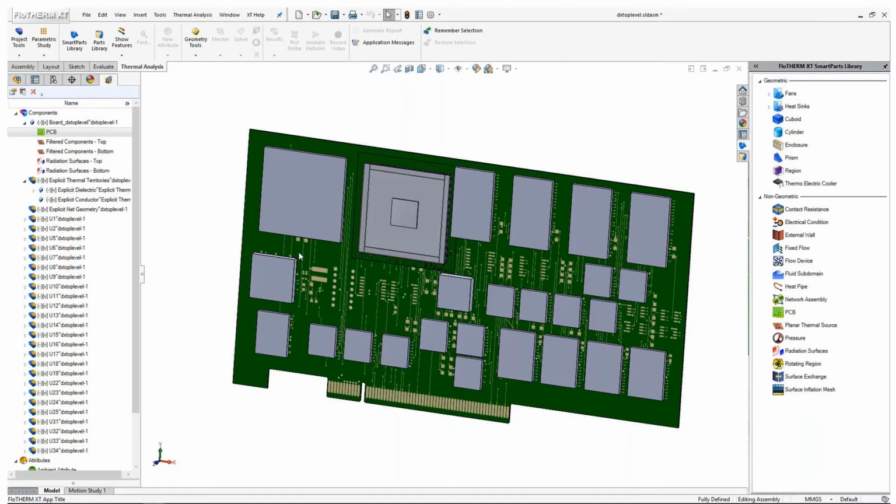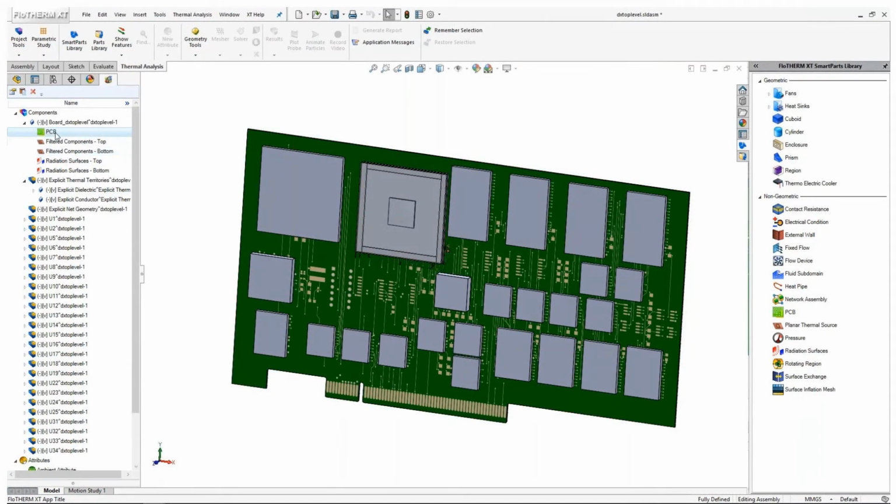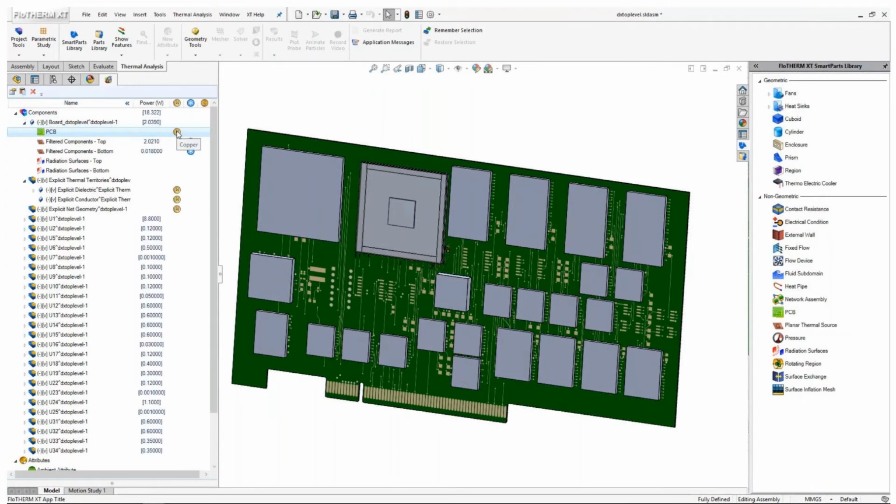So to summarize what we have done so far, we have the material definitions assigned on different components that we have, thermal attributes assigned, and we got the total power defined as well using the CSV file. So let's look at the thermal territory which we have over here. Before that, let's have a look at the attributes which we have. We can see that what we define in the Flow EDA bridge gets reflected here. We have the material properties, the thermal properties, and all our powers reflected over here.